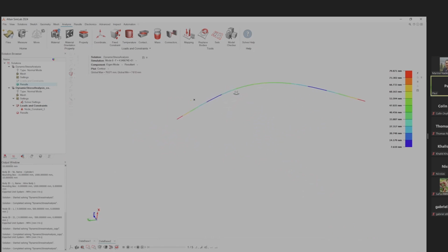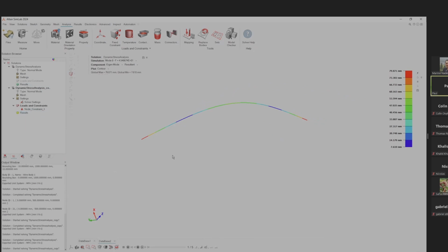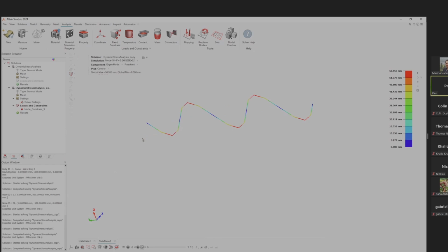So if you constrain the model somewhere, like in my second analysis here, or update this one, if I add a constraint, my first normal mode will be higher than 0. So my first one is, I don't know why it's e to the -4, but this one, I guess, is still low. Yeah, they shouldn't be, but remember this is hertz.